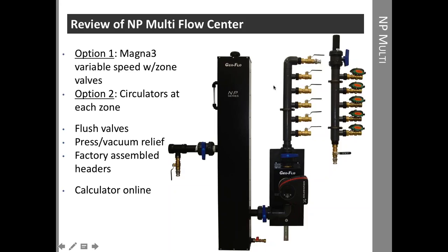So those are the connections to the flush cart, and there are ball valves at each of these connections. So it allows us to purge air from the system pretty easily, and that's all factory installed, including the cam. So there isn't anything that has to be changed at the job site.